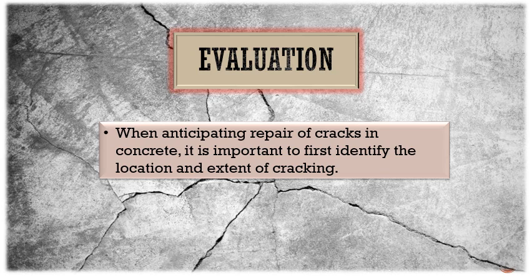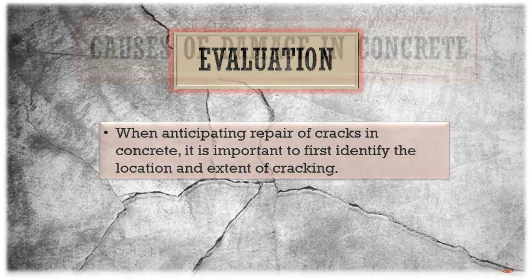Taking into consideration the present and anticipated future loading conditions, the cause of cracking should be established before repairs are specified. A field investigation and a structural analysis should be completed before proceeding with repairs.